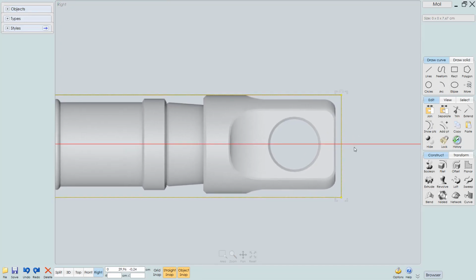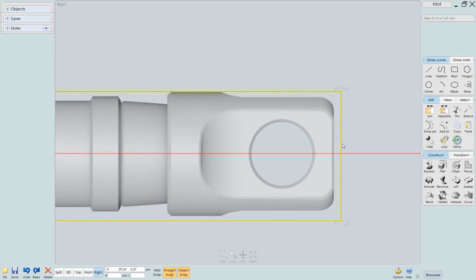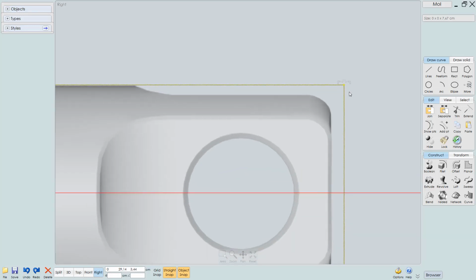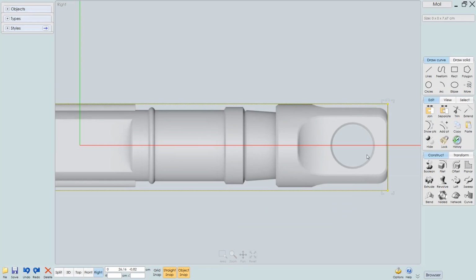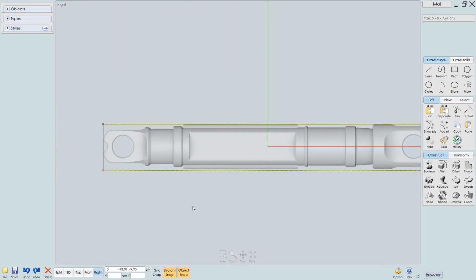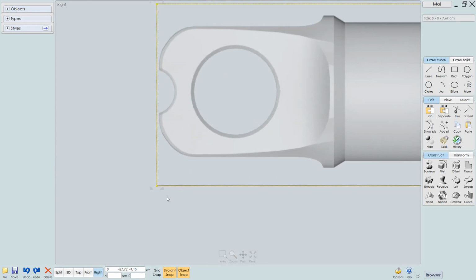And what I did wrong in one of the previous videos was when I had selected the points, I tried to click on this line and move them around. And in Moment of Inspiration, that's not really what you should do unless you want to change the shape of that curve. So with those points selected, left click on one of the points and drag. And doing it like this, you will make sure that you only move the points and don't change the shape of that curve. Left click to deselect all the points, and let's go ahead and select these ones. I will move these over a bit as well.